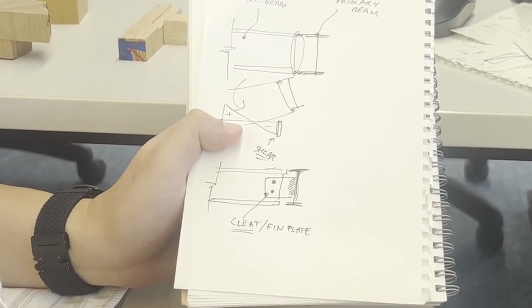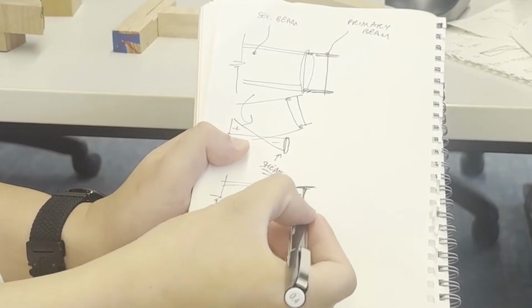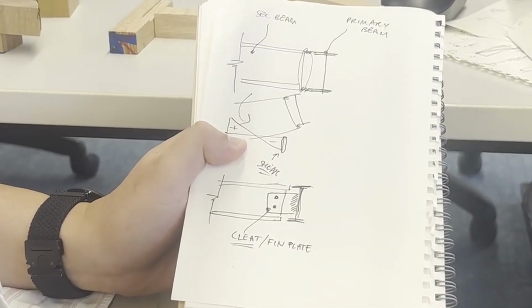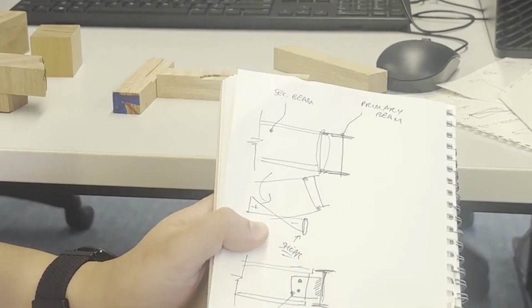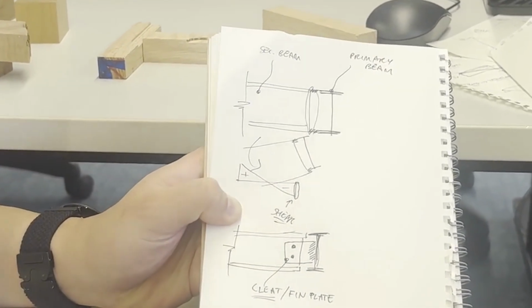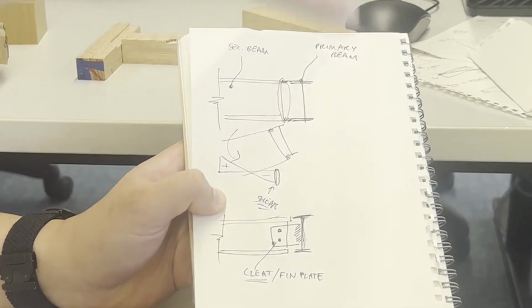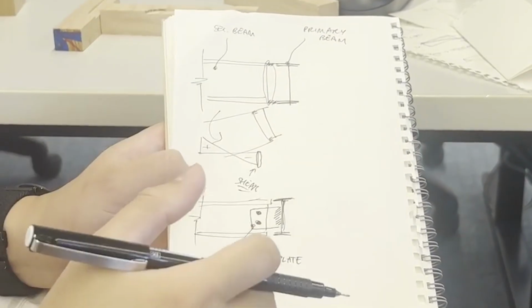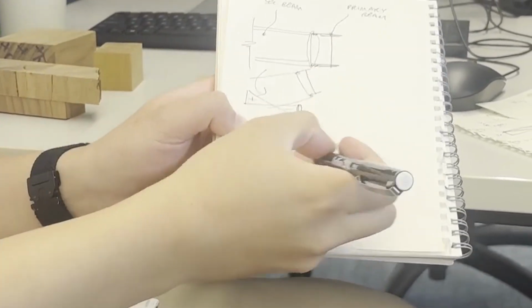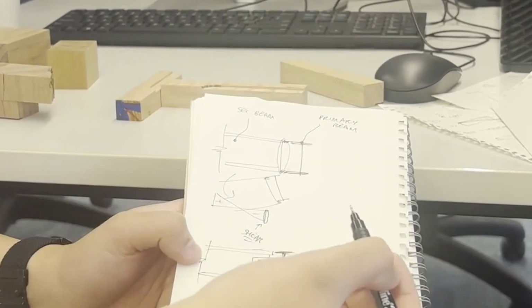You want to do something called shop welding, which means in the factory, when they're preparing the beam, they have qualified welders there, which are very expensive, with a very high rate. You want to do all the welding in the shop. You don't want to hire a welder specifically to go to site to weld the other side. So you get these tradies, these steel fixers, to just complete the bolt component. You leave a bolt hole, and then you give them the bolt, or they supply the bolt themselves, and then they tighten the bolt, and now these two parts are connected together. So one side generally bolted, the other side generally welded.